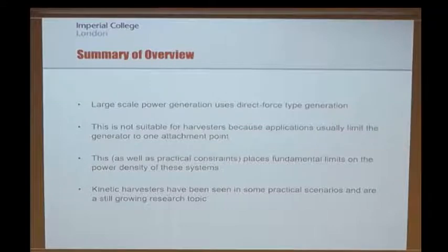And as I say, the energy that we're able to generate is the integral of force times distance, integral F dx. You can immediately see on this basic mass in a box energy harvesting model that if you make the transduction force too big, then the mass won't move. It'll just stay still inside the harvester and you won't generate any power. But clearly if you make the force too small, then you'll get a lot of relative movement of the mass inside the box, but because the force is small, your overall power is small as well. So this is why we are interested in optimizing this value.